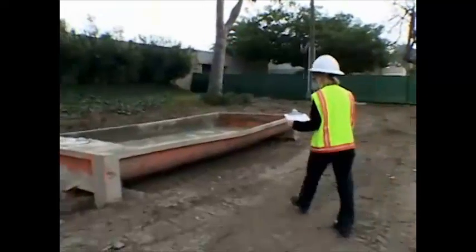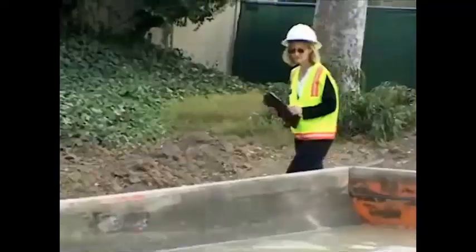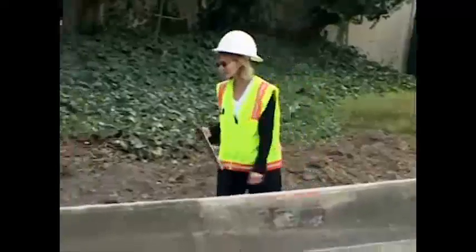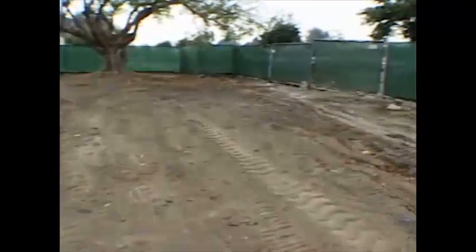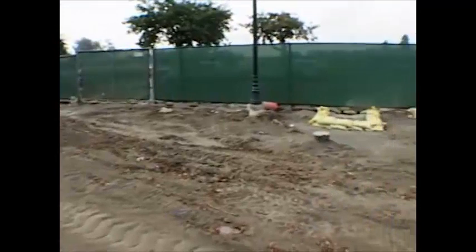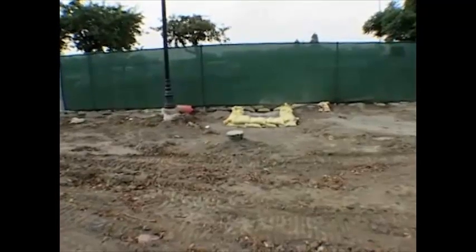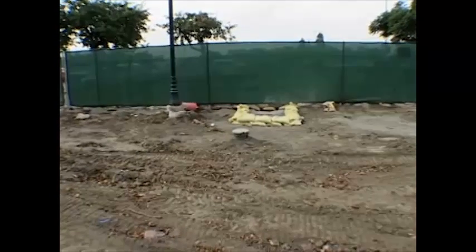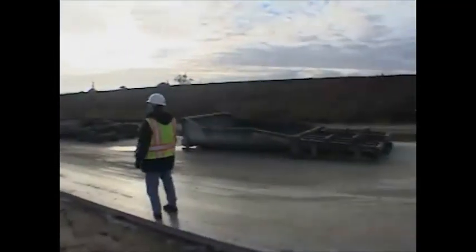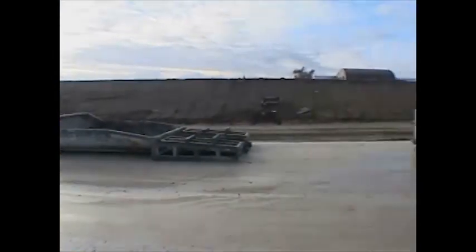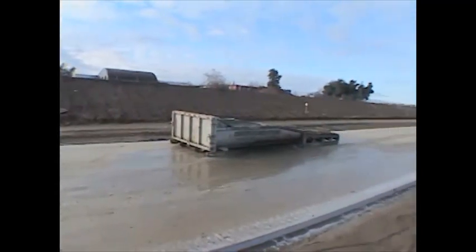Carefully plan the location of the concrete washout by walking the site and reviewing the site plan to choose an area best suited for the concrete washout. When determining the location of the facility, remember a concrete washout must be located a minimum of 50 feet from storm drain inlets, open drainage facilities, and watercourses unless determined infeasible by the resident engineer. Also, locate the washout facility away from construction traffic or access areas at a location determined by the contractor and approved by the resident engineer.